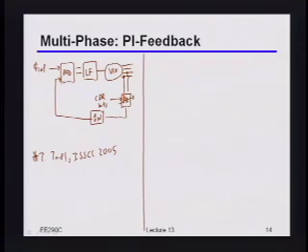And by the way, this is kind of a subtle thing, so we'll see if anybody can throw some wild guesses out there. Can you keep muxing between certain phases? Okay, you could do that. You could basically pick one phase on one clock cycle, and on the next pick a different phase. You could indeed do that, and that actually does work.